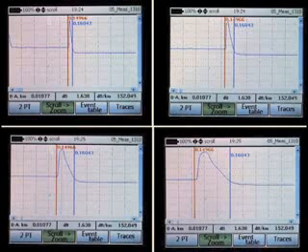Here you can actually see the same trace taken with 4 different pulse widths. On the lower left-hand side was the 25 nanosecond pulse that was chosen by the auto test. On the lower right side is a 100 nanosecond wide pulse, which is appropriate for very long cable plants.